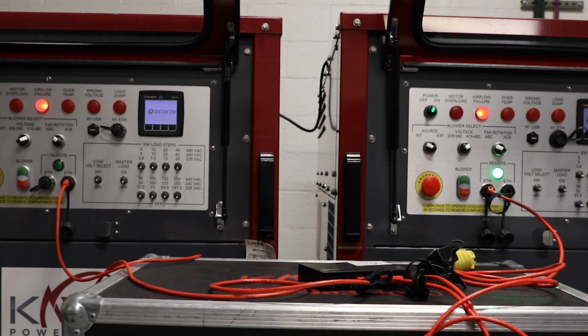While we have buttons for up to 100%, we can also manually enter in load steps above 100%, provided they are less than the safety max that we set up for the group. Lastly, you can type in the amount of load in kW that you want in the target kW field. In this case, I want to start at 0, so I'll select 0% from the presets and click Apply Load. Don't worry, selecting Apply Load doesn't apply the load to the load banks right now. It simply programs that step.